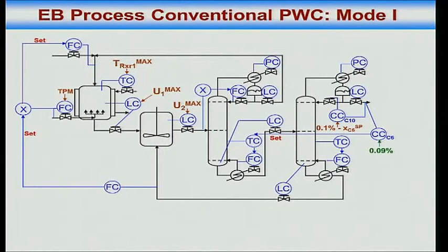So I just took that structure. Okay, now throughput manipulator is the fresh ethylene. You jack the throughput up. These green arrows are your unconstrained degrees of freedom. 4 unconstrained degrees of freedom, 4 green arrows. Total the DEB recycle rate 1, the reflux to feed ratio in column 1 2, the benzene impurity 3, and the temperature set point on the second column 4 degrees of freedom.